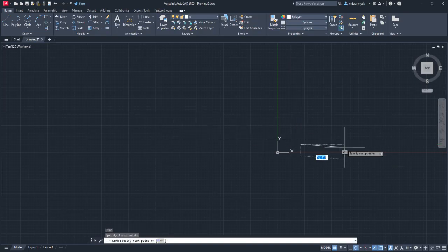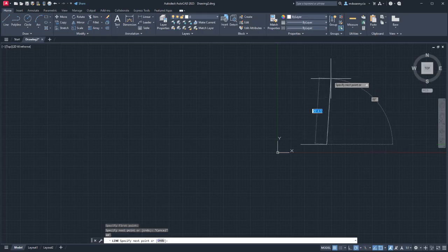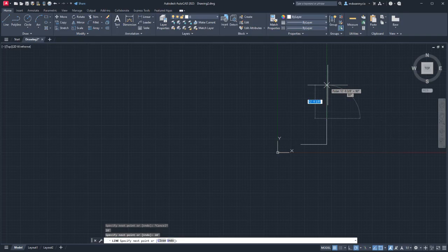Most commonly, though, you will basically be walking around your model in a way where, at least the way that I generally do it myself, I move it off in the direction it's supposed to go, let it snap using those snap tools, type a distance, hit enter, move it again, type it and hit enter. When I used this daily, I used to be good enough that I could actually do the coordinate entry or the angle entry very quickly, but I'm not that good at it anymore. It's one of those skills you sort of have to keep up with. All right. So with that in mind, let's talk about some of these tools down here, and then we'll get on to the rest of these.